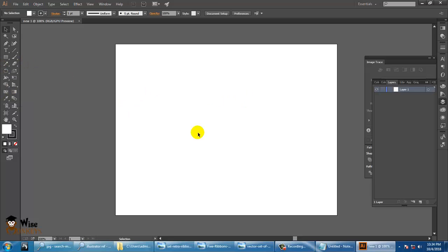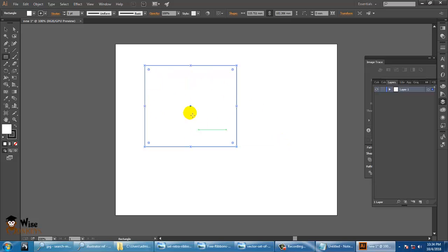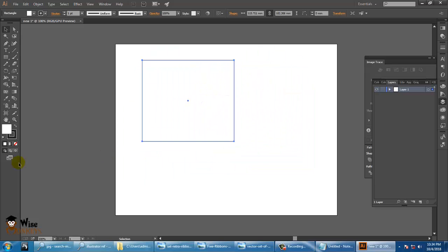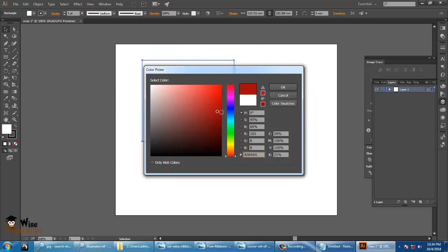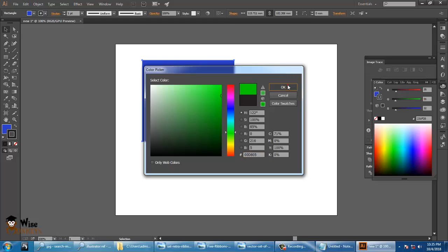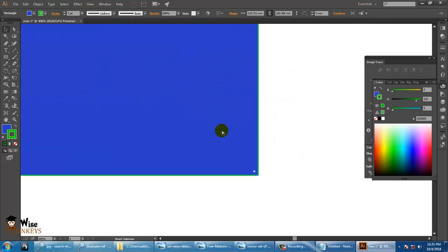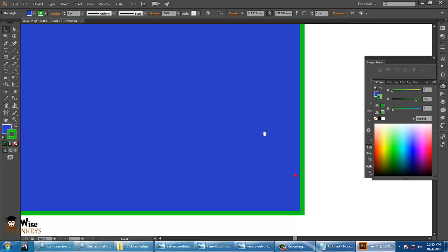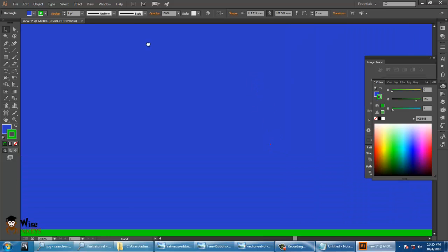So now let's start. Let's take a rectangle tool over here. So if you make a rectangle tool over here, so you have made a rectangle over here. You have a tool called selection tool. You can move the selection using the selection tool. You have a fill color. So fill is your fill color. You can fill a color. And this is your stroke color. Stroke is your border color. So if you need a border color, and if you zoom it, you will not see any pixels. You won't get any pixels because this is a vector application.